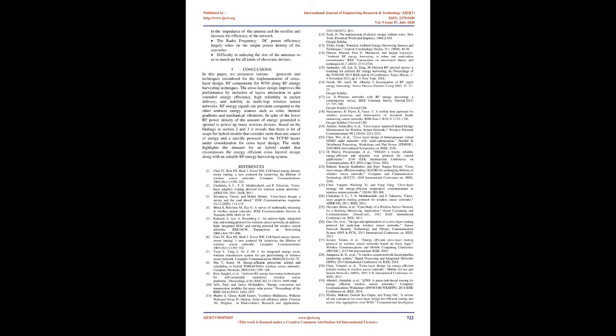Safri et al. 2019 proposed an RF converter scheme with a 4-stage threshold voltage compensation circuit that uses sub-threshold auxiliary transistors to achieve higher PCE. The rectifier is designed in 130 nm CMOS technology. This technique can be applied to a link of considerably reduced number of rectifier stages.